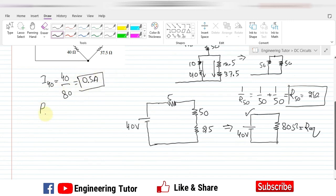Similarly, the power provided by the 40 volt source is equal to I40 multiplied by 40, which is P is equal to IV. So by using the values here, 0.5 multiplied by 40, so this is now 20 watts. Okay, so this is the overall circuit, and the actual